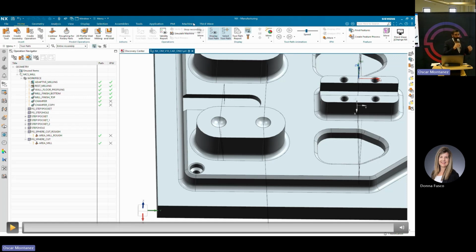There's ways in which you can have one database with a bunch of operation rules that you set up. So you can say that if the tool is this material, because NX has that information about the tools, if the material is aluminum, titanium, whatever that you're cutting out of, you can choose to set up an equation within your database that then chooses the appropriate strategy to cut from. So what I'm saying is there's multiple ways that you can set this up according to how you would like to set it up.